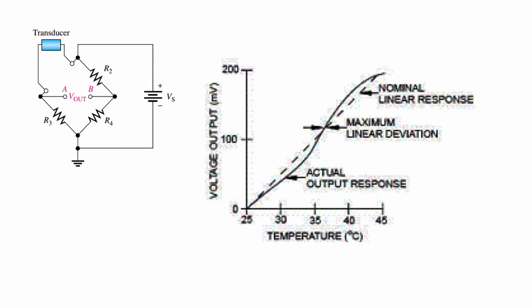In one of the experiments you are going to perform, you will be tasked to make an electronic thermometer by using a Wheatstone bridge and generating a calibration curve, such as the one that's shown. The change in resistance of the thermistor causes a change in the output voltage, corresponding to the change in temperature. This change may be linear or nonlinear, depending on the type of thermistor. Such a type of circuit is very useful if you want to digitize your thermometer.